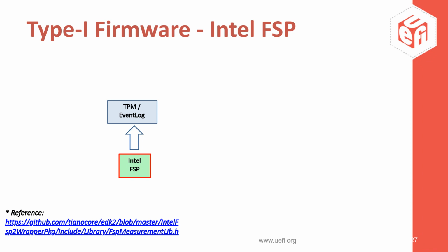look for. And so now you're in the field. You're booting your firmware. The OEM has integrated the FSP. How do you assess what the provenance or the identity of that specific FSP is in your system? And that's where this augmentation of the measured boot happens. And so we provided an example code that could be used in EDK2 that actually generates the event logs described in the TCG specifications and the prior slides' 2.x measurement spec.